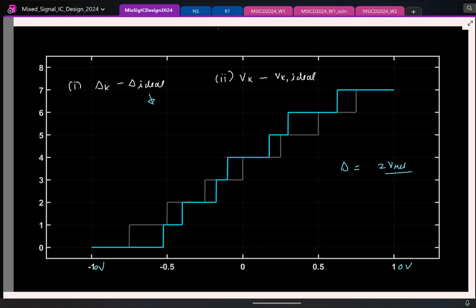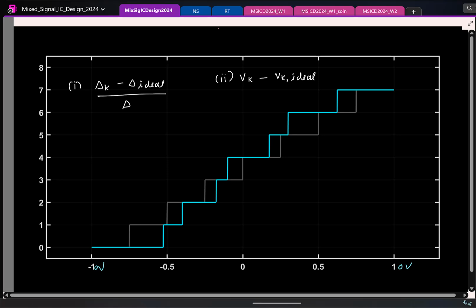See, this is basically stretched out, everything stretches out, everything increases, but 10 times is not what you expect, right? It doesn't mean that the quantizer is more nonlinear. It is the same fellow, just that I am changing the reference voltages. So there is no point in looking at the absolute deviation. You have to normalize it, and it's normalized with respect to the ideal step size.